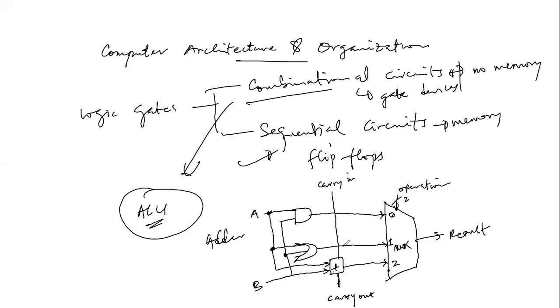So, well, this is a simple ALU, okay? And then we know the operation here is a two-bit value, and this selects the operation that will result in the result. Because for your MUX, we have multiple inputs, and then we have a single output, then we have the select button, okay? And the select button here is performing this operation.